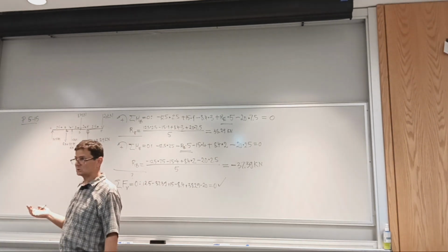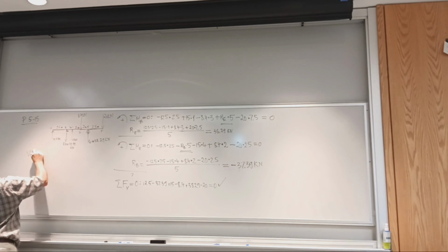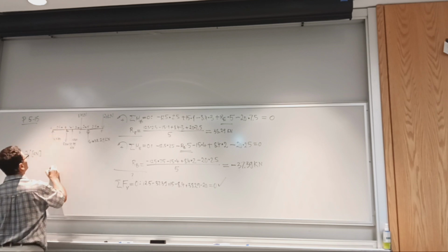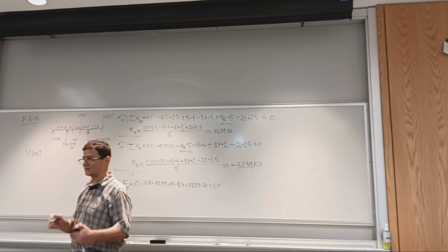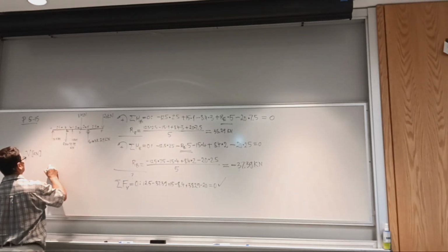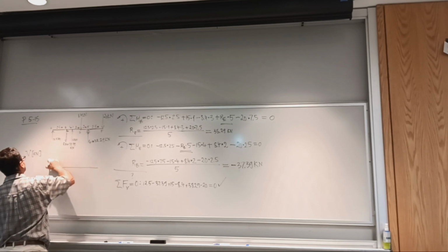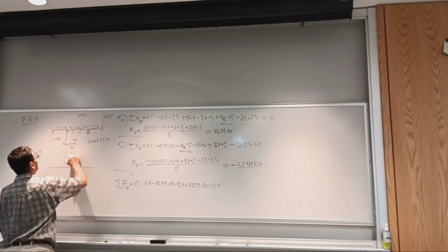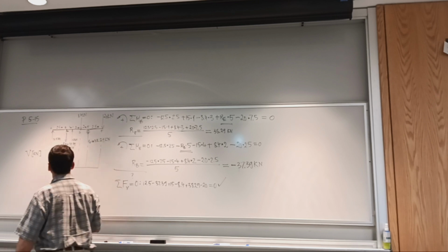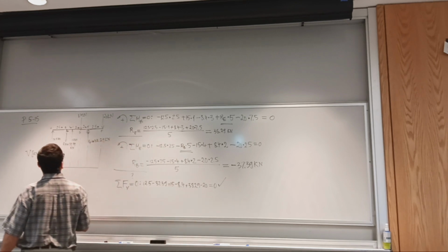We show the shear diagram, and it will be V, in kilonewtons. We'll stay with kilonewtons, not to carry zeros with us. We'll be both above and below the graph. Here, for moments now, I cannot tell the beam is smiling, so make sure you manage the paper space that you have to accommodate possible negative and positive of both. I'm aligning the shear diagram with the load diagram, because things will happen at points A, B, C, D, and E.